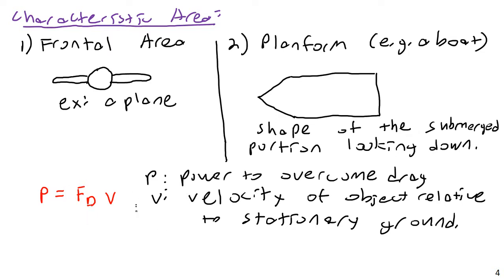But once you have that, to calculate the power required you need to look at the absolute velocity V, or if we're talking about a plane, this would be the ground speed of the aircraft rather than the airspeed. And where this comes from, again, if you think of this, work W is useful energy. So V relates to the useful work.